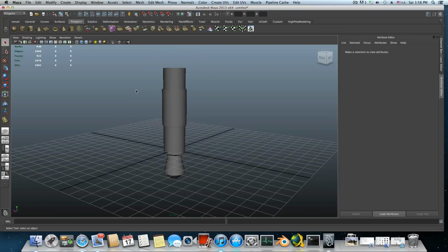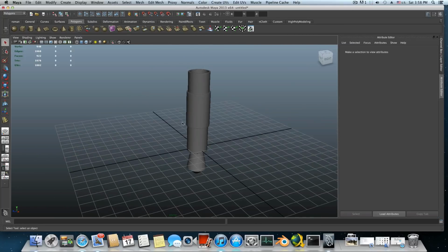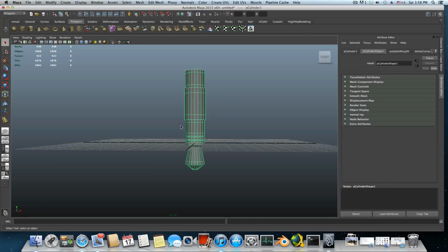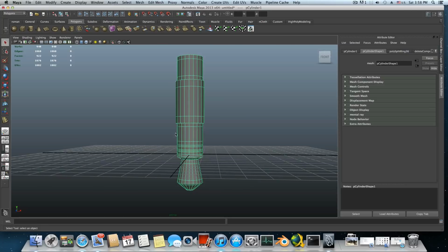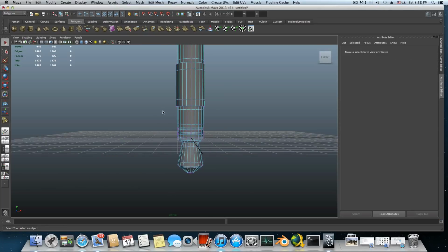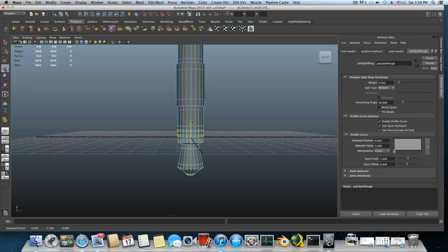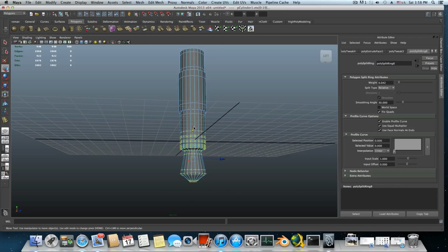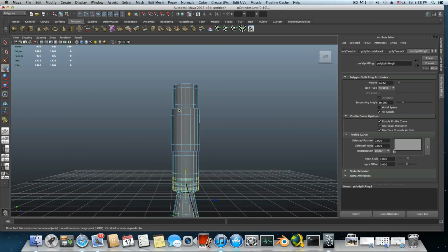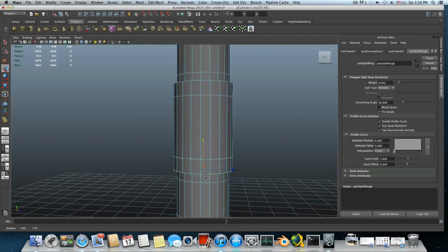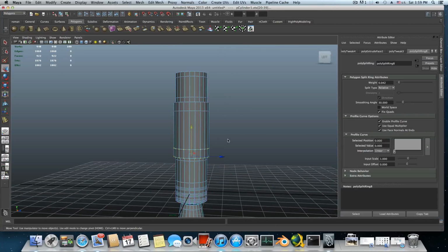So that's great. Now we may need to modify this scale or some length and things like that, but whenever you do this, make sure you do it when you are in the non-smooth preview mode. Okay, so make sure you press 1 and then you modify those things. Like if you like to make this part just a little bit more long, be aware you need to grab all these vertices and just pull them at the same axis direction, okay? And if you want this plastic area to be more long, grab all those vertices. You see, I'm grabbing all those also at the same time and bring it over here. Tap on F8, bring it back to object mode.